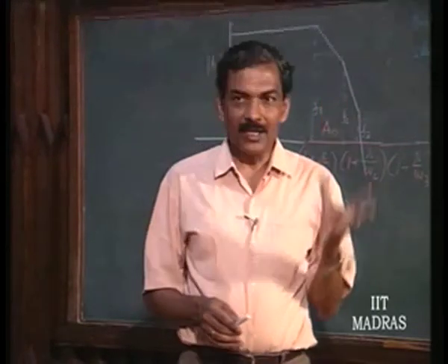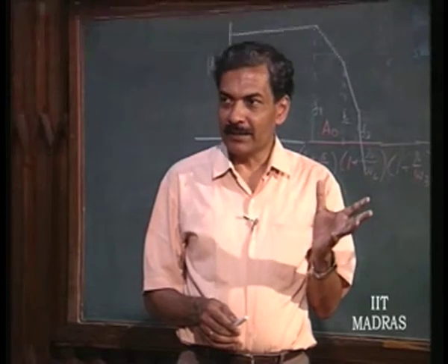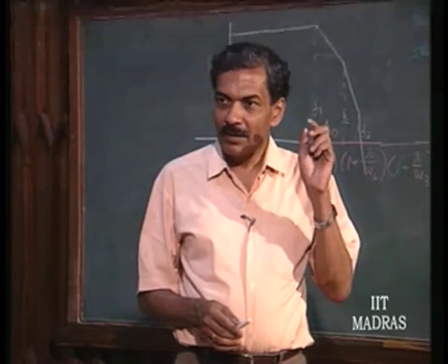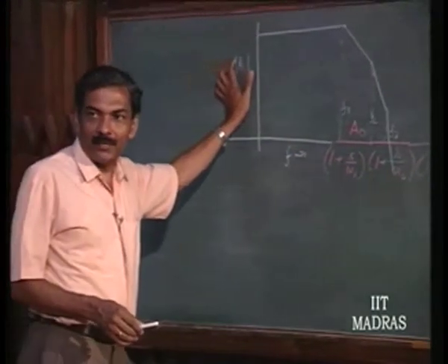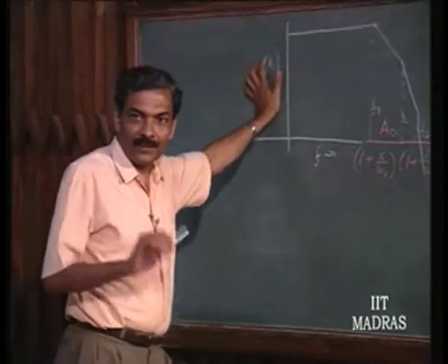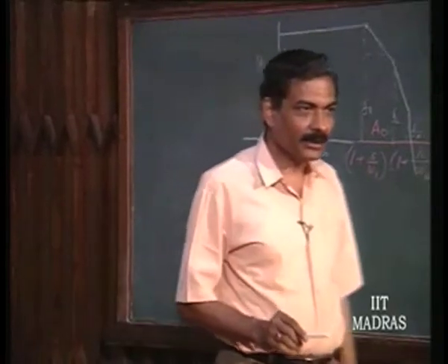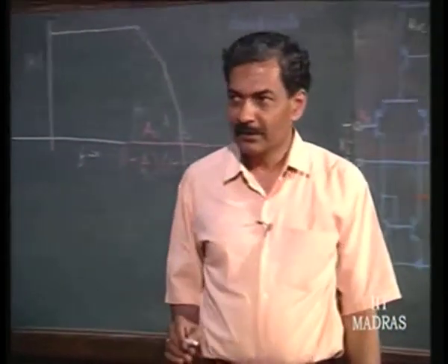Okay. So, a general purpose op amp is designed for making this A become less than 1 when the phase shift of the entire thing becomes equal to 180 degrees.